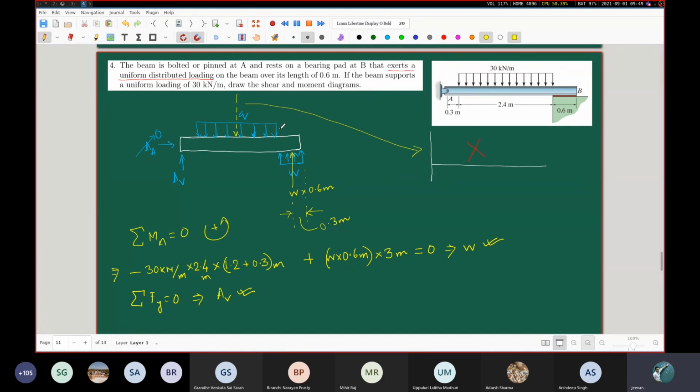Rather, you are supposed to proceed from the actual distribution of forces, like this. Why is it important? Because if you have a beam like this, and there is a concentrated force like this, then if you take a cut section here, the shear force in this region is a constant value because of the V being balanced by this reaction force.